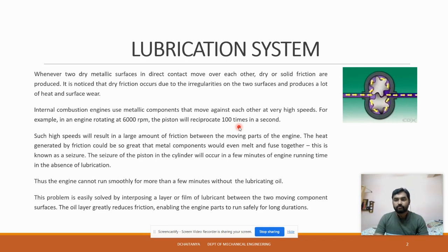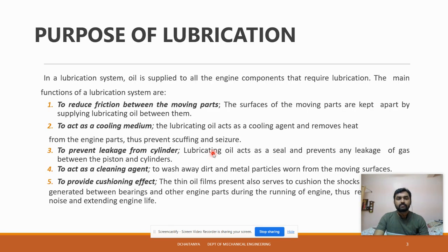It has a fluid property that you all know, that is viscosity. Here the viscosity index will be maintained with respect to temperature. Fluid particles with higher viscosity will resist one layer moving over another layer, as you all studied in fluid mechanics. That interposes a layer or film between two moving components, which helps to reduce friction. Finally, our objective is to increase the engine's durability over many thermodynamic cycles of engine operation.